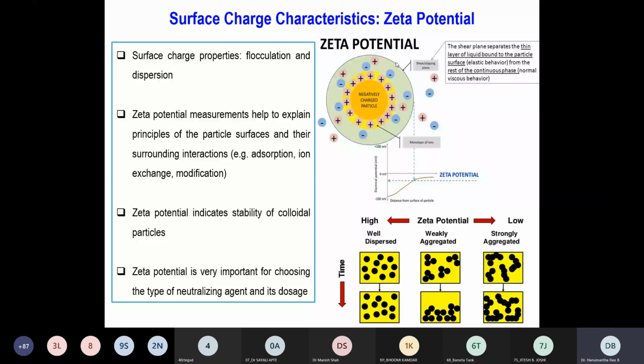This zeta potential gives an understanding about the charge capacity of that particular material, and this charge is induced by several aspects. In soil mechanics, in the case of clay, the charge is because of the negative charge, while in the case of red mud, it may be because of the presence of oxides, or because of the presence of broken bonds. As you vary the pH, because of the addition of the additive, you accentuate the phenomenon called flocculation or dispersion.